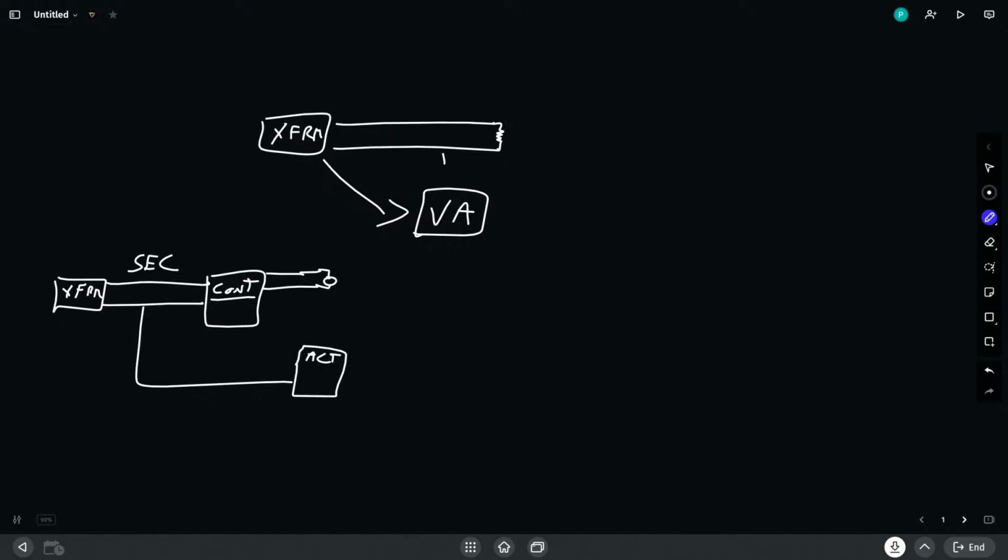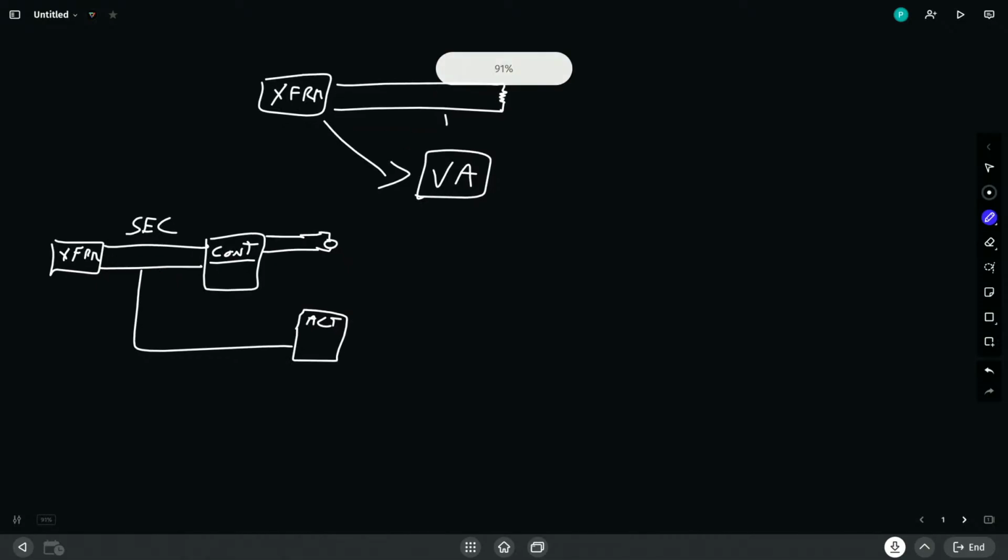Now, on a controller, if we were to bring up a controller catalog sheet, it would say an unloaded controller maybe requires 14 VA, but requires 40 VA when it's fully loaded. That's because the controller is sourcing voltage to drive outputs, and as it drives outputs, those outputs have certain amp ratings and voltage ratings, which then decrease the VA capacity of the transformer.